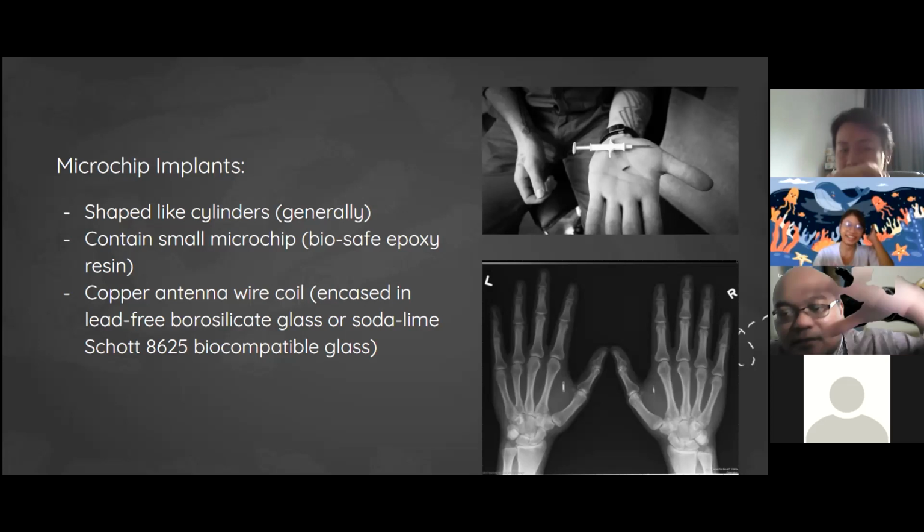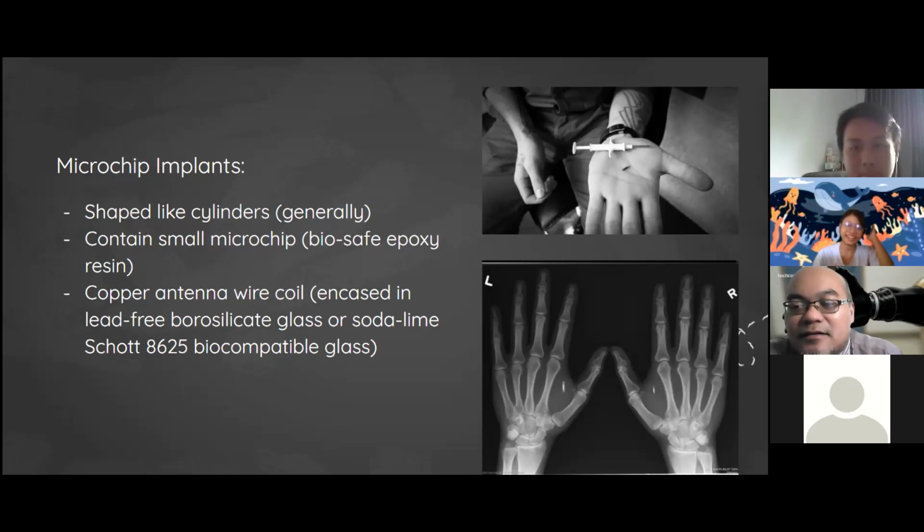That is why the enclosure could not be metal. It is made here from epoxy resin. Why did you choose epoxy resin? Why not other ceramics, for example? That has to be clear in the choice. Similar to group one: the dental implant has to endure chewing stress and grinding shear stress. In your case, what kind of mechanical property requirement does it need to have based on this particular application? You list them first, maybe quantify them. Then what are the choices of material? And finally, the most optimal material is this.